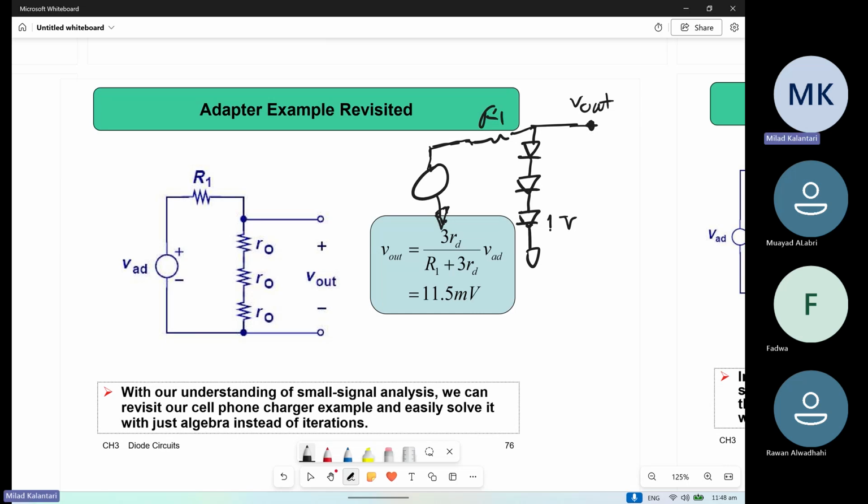If we stack up 3 of the diodes, how much would be this V out value if each VD on is 1 volt? 3 volt, right? Does it depend on the input voltage? Here you have some input voltage first, right, to turn on these diodes.